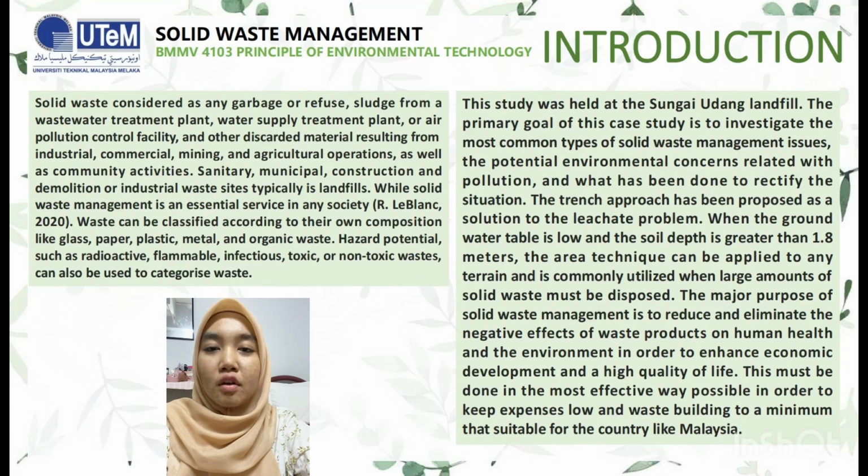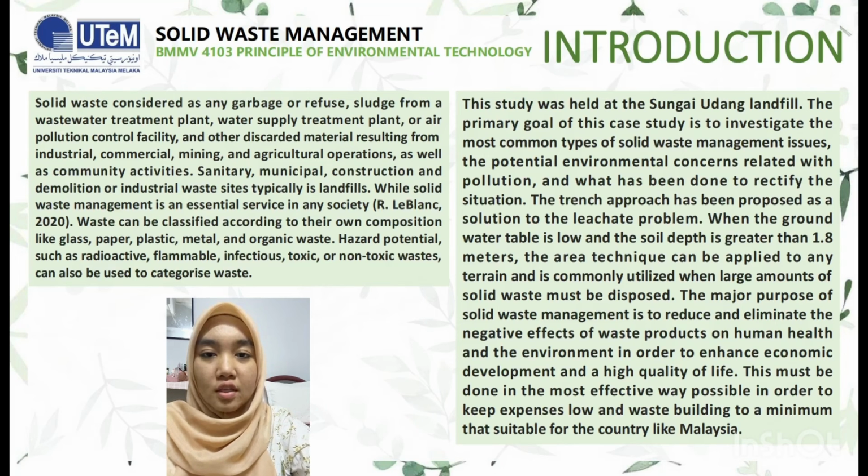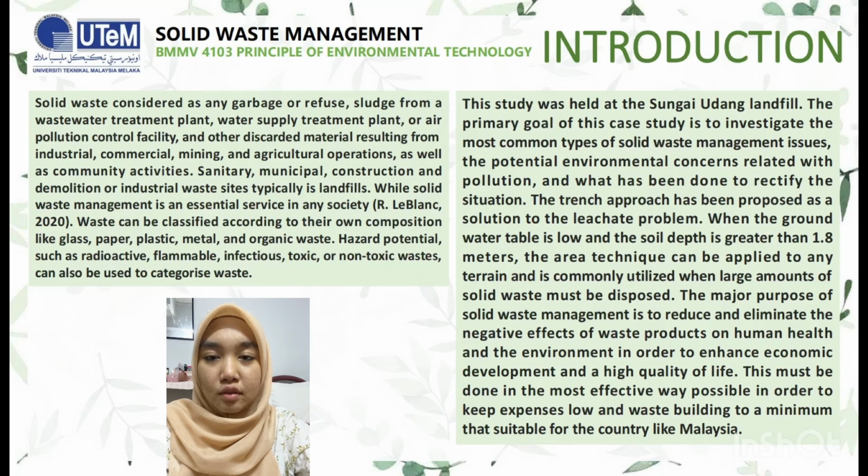We chose Sungai Udang landfill to conduct this case study. The primary goal of this case study is to investigate the most common types of solid waste management issues, the potential environmental concerns related to pollution, and what has been done to rectify the situation. The trench approach has been proposed as a solution to the leachate problem. When the groundwater table is low and the soil depth is greater than 1.8 meters, the area technique can be applied to any terrain and is commonly utilized when a large amount of solid waste must be disposed of.